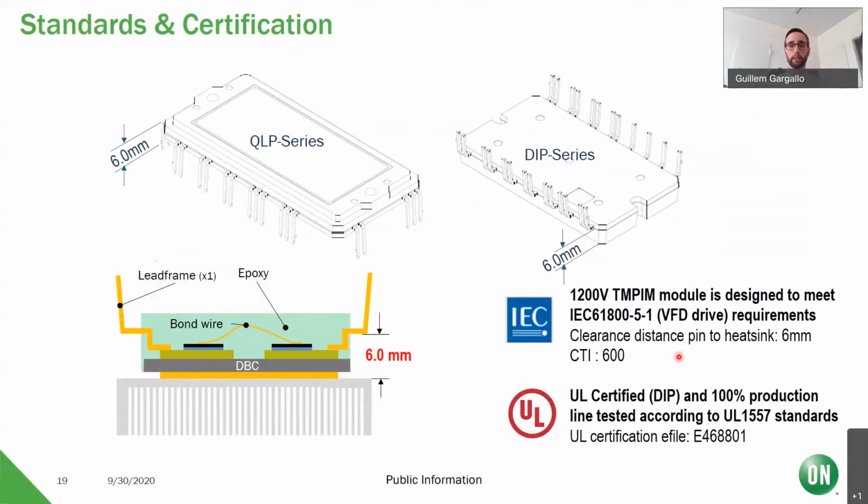The package material is CTI 600, which also enables us to meet the creepage and clearance distances between the different potentials from the different pins, also reducing the module size. And of course, our modules are in line with UL 1557 in terms of production test. And we have here also the UL certification, where you can check the file later on as mentioned here.